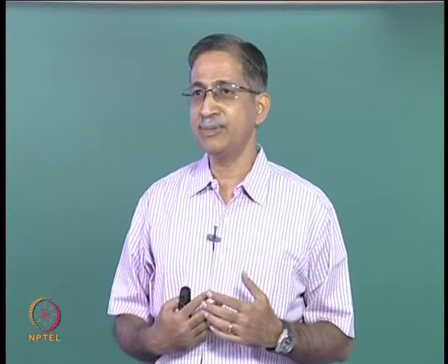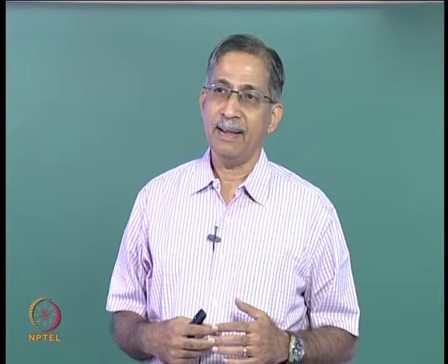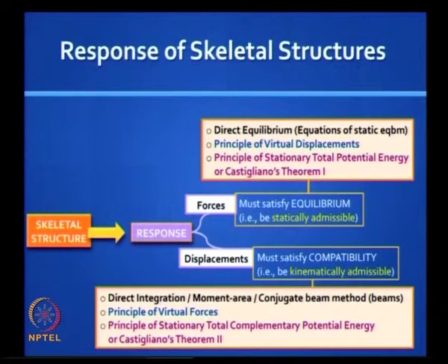So your correct response must be both statically and kinematically admissible, and there is a third requirement, that the force displacement relationships should be satisfied, which in turn depends on the constitutive relationships in the material, the stress strain relationships and so on.